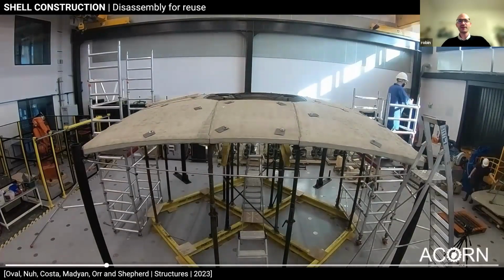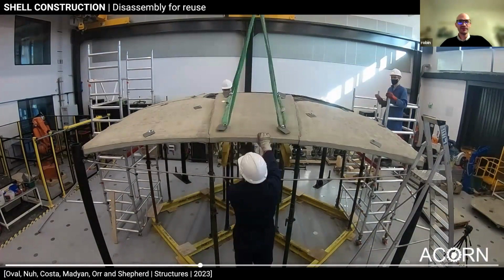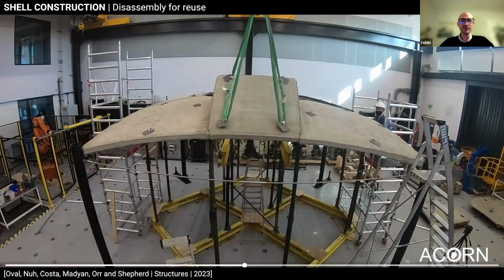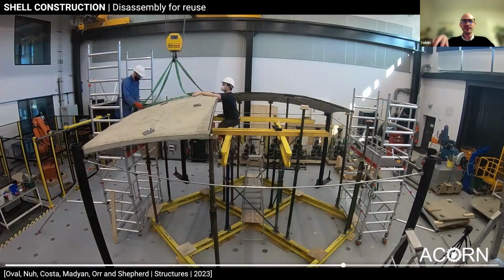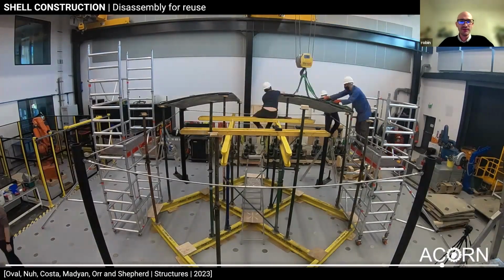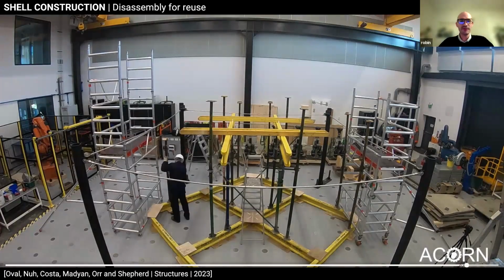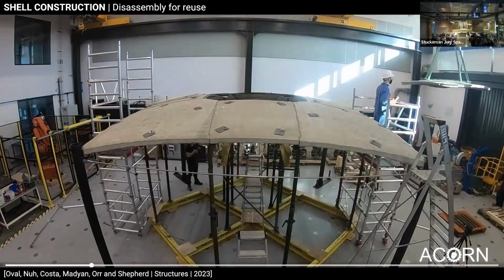Okay. So here we had to put the telescopic props back, push up by a couple of inches, and then remove the elements. So first the oculus, like the central piece, then take care of one side of the boundary, etc. So that shows how, in reverse sequence, we assemble it. That was the easiest part of the project.